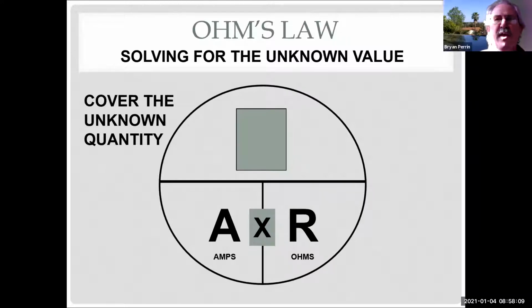If I have current flow and I have resistance in the middle of a circuit, and I'm measuring before and after the resistance, I'm going to have a difference in voltage. If I have no resistance, but I have current flow, I won't have any voltage. This is actually how we test for bad battery cables or bad wires. We don't use an ohm meter; we actually use Ohm's law in voltage. We measure for voltage, knowing that if I have any voltage while I have current flowing, there has to be resistance. Otherwise, there'd be no voltage.